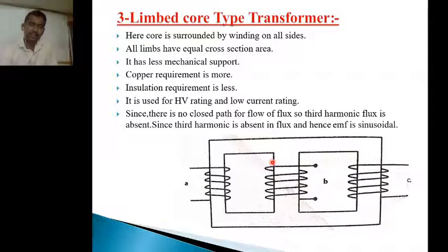So there is no talk about the third harmonics while drawing the magnetizing current from the transformer primary winding. During load operation, the transformer draws a larger amount of current. At that time some harmonics will be developed. Third harmonics and fifth harmonics, all the harmonics are present, but we will consider the effect of the third harmonics only.